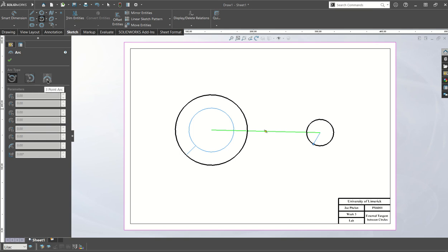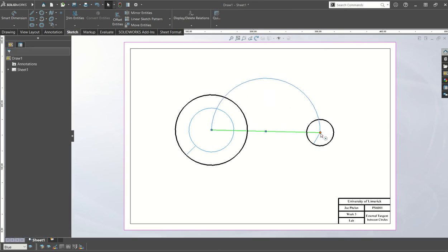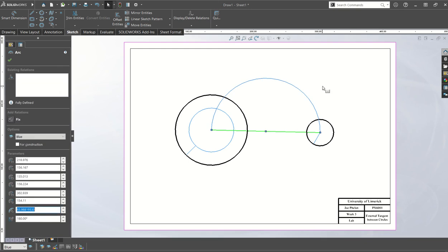And when I've got my 3-point arc, my first point is the first point of my arc, the second point is the end of the arc, and the third point is the other point in the arc that defines the radius of it. But for my center point one, the center is important, so I'll use that. I'll click on the center first, and I will click this to be the beginning of my circle, and this to be the end of it. And you can see here that that's fully defined again, and that is all within those bounds.